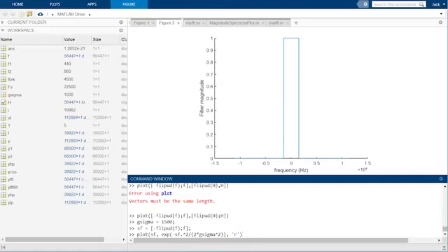There is also traditionally a scaling factor used to normalize the integral of the Gaussian function. However, this is often ignored for signal processing applications because it is often more convenient to retain the maximum value of 1 where the argument of the exponent is 0.